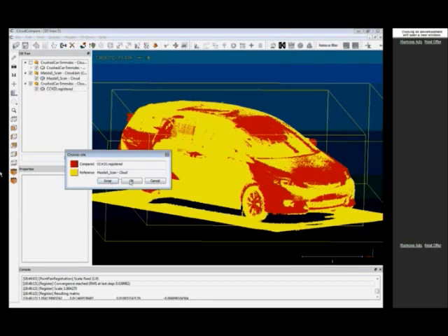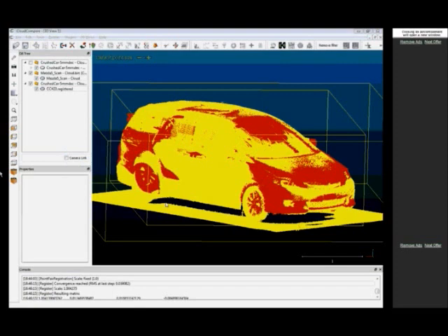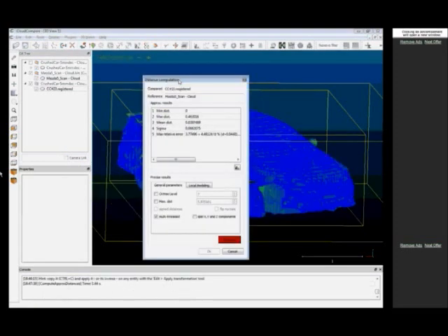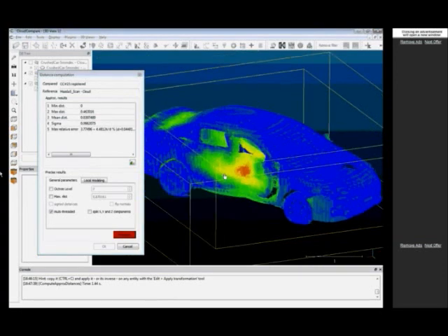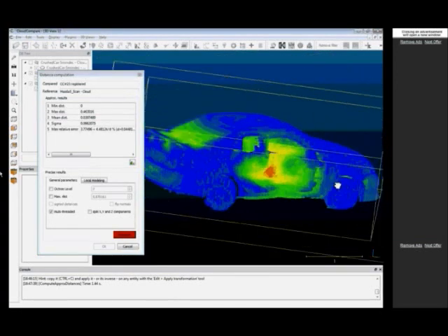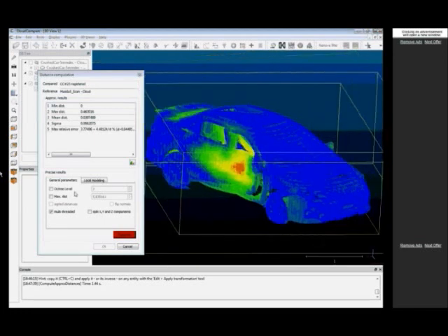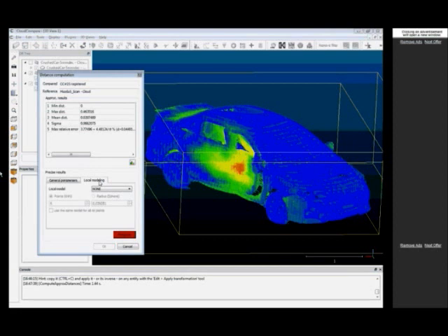First, CloudCompare will perform a very approximate distance computation. It's only for it to be able to set parameters, quite tricky parameters that the user won't be able to set itself. You can also apply some more parameters like local modeling. I'll talk about this later during my presentation. Anyway, generally, you just have to click on the compute button.